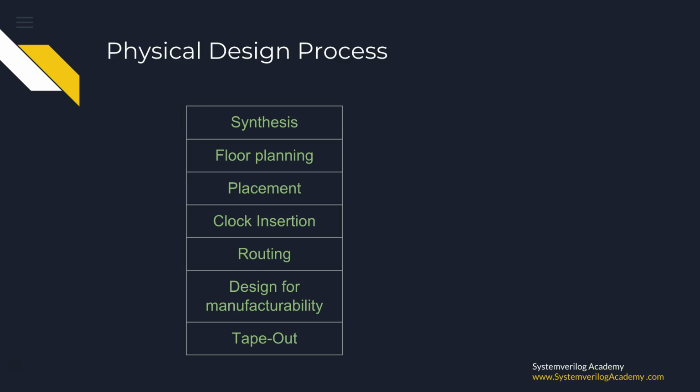Clock insertion phase. Here, clock signal wiring is introduced into the design, which is commonly known as clock trees. The clock signal needs to be driven to every part of the circuit, with the capability of gating the clock as and when needed. Clock gating is a process of saving power by shutting down a part of the circuit when it is not active for a small period of time. The clock tree is a metal grid, which distributes the clock signals from a common point to all the elements that need a clock, considering the clock gating.